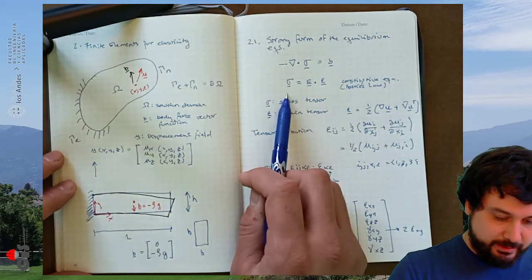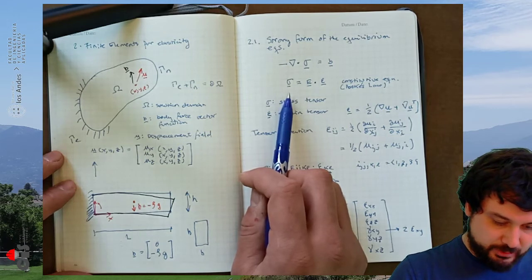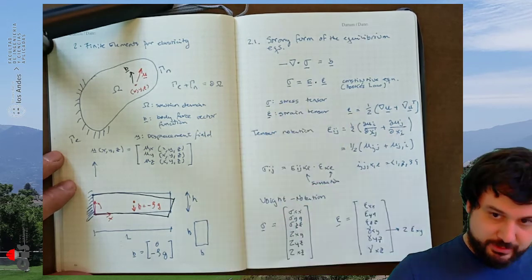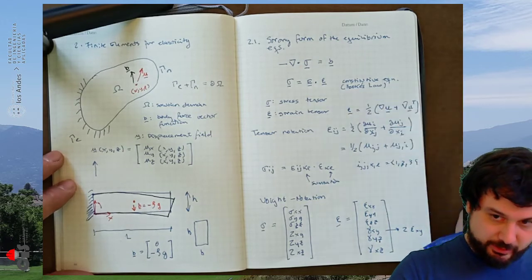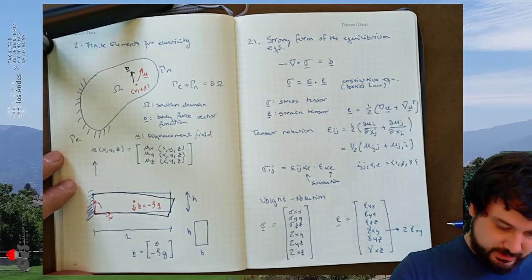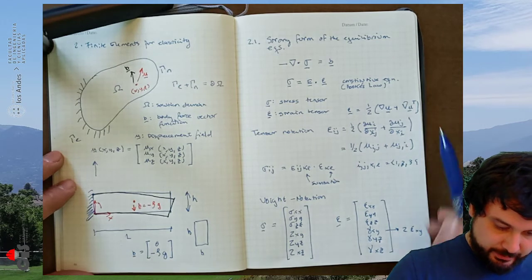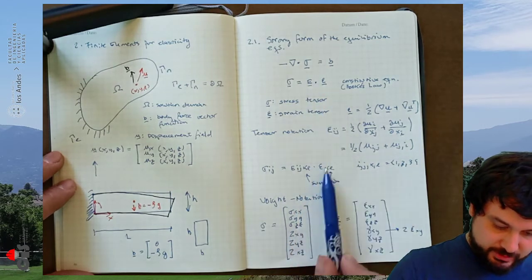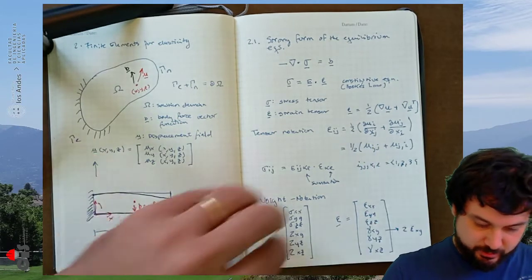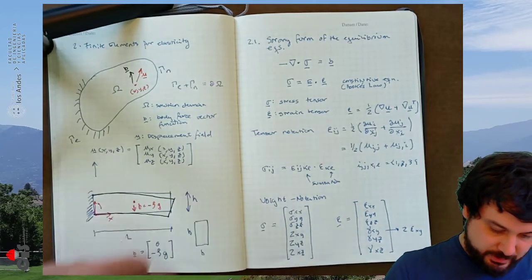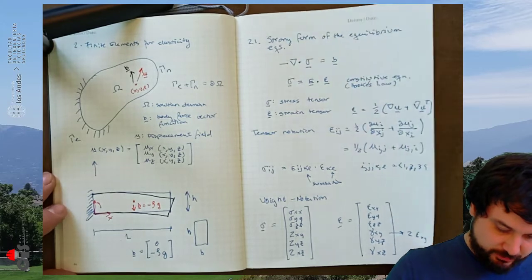To that we add the constitutive equation, Hooke's law in this case. We'll write this down for a couple of particular cases, 2D and 3D elasticity, in just a sec. But then the strain tensor is what has the displacement field inside, so that's what gets you over there. And we're adopting this so-called Voigt notation.